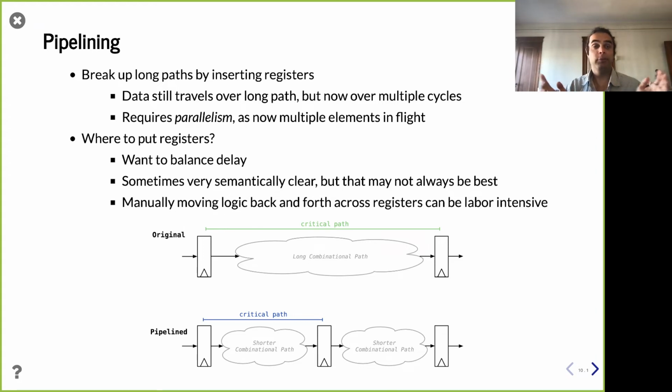Okay, if I have millions of pixels, I can do some of them over time, on different cycles going through the same hardware. I can do some of them in space and just have parallel units processing different pixels, right? So, like I said, fortunately, in things other than processor design, there usually is quite a bit of parallelism, and pipelining is not so hair-pulling. But it's still not easy. It's still not always trivial, right? Sometimes there are some caveats, some challenges to it.